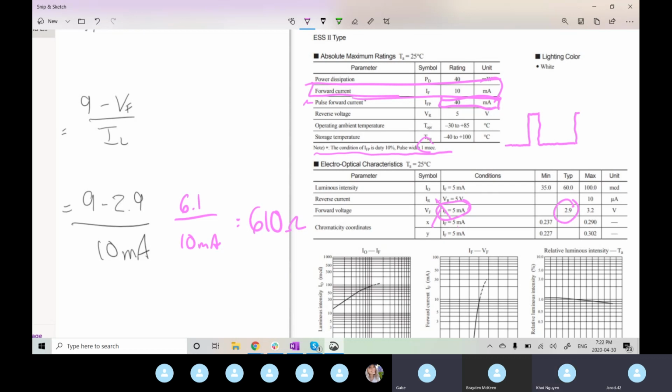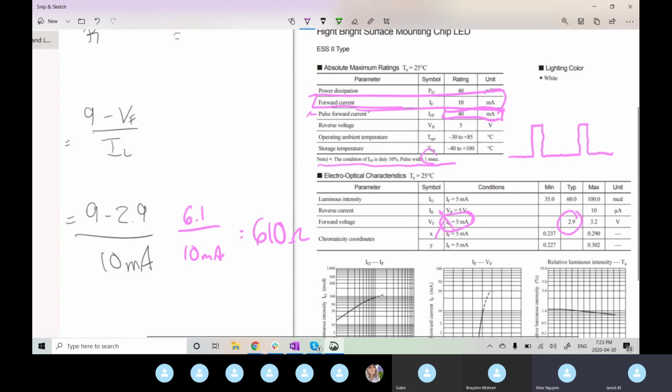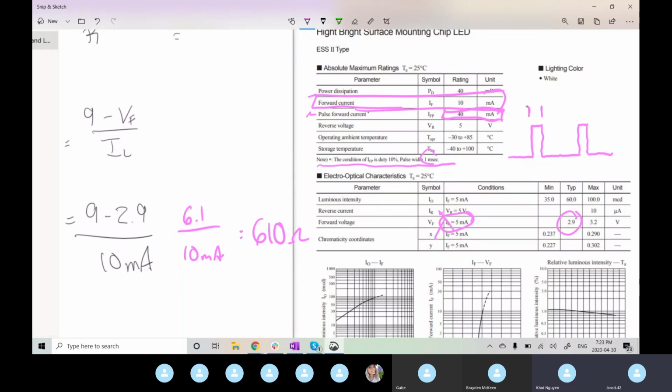So when they're talking duty cycles of some percentage, it's the on time of the entire cycle. So from edge to edge is your entire duty cycle. So if we're only on for this small sliver being 10%, and they're saying the pulse width 10% equates to 1 millisecond.